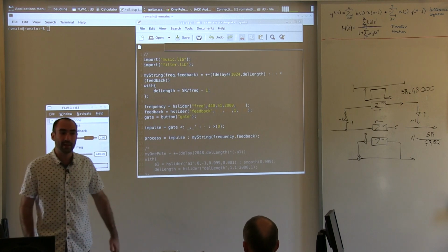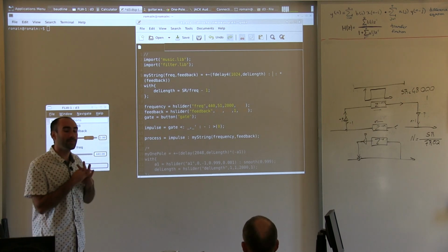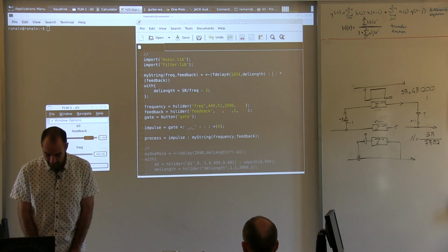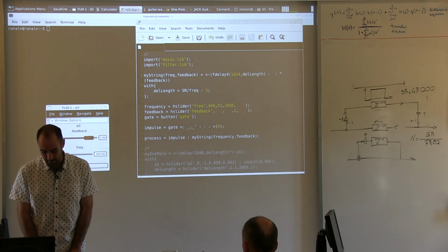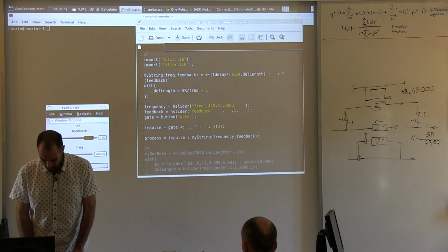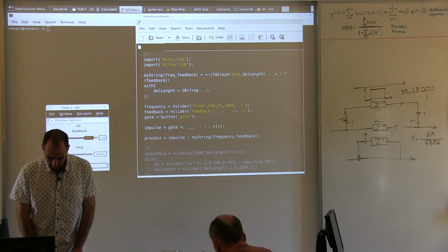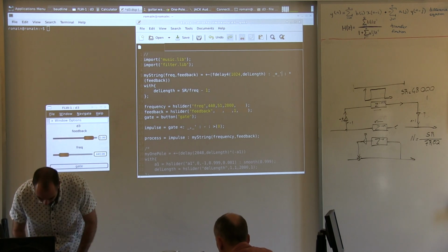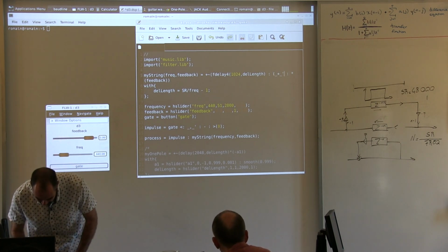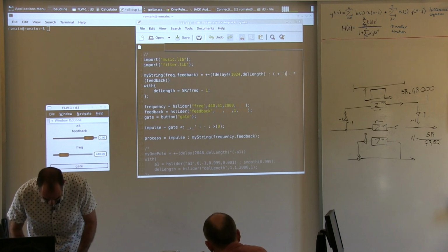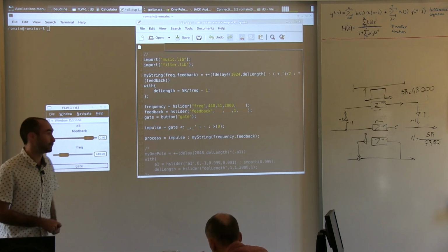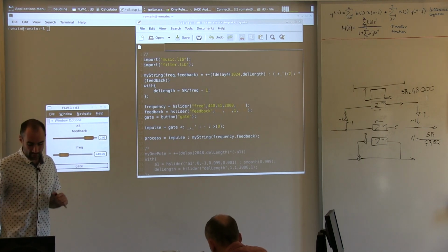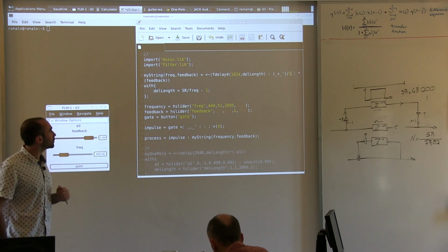And in this new step, we're going to design a very, very basic filter. This very basic filter is basically just going to be the signal added to the signal delayed by one sample. I'm going to have to put parentheses, divided by 2. And that's how they did it in the, like, early days.